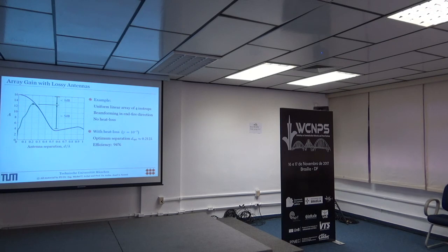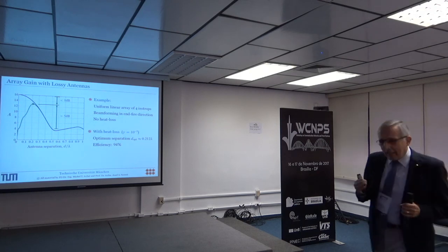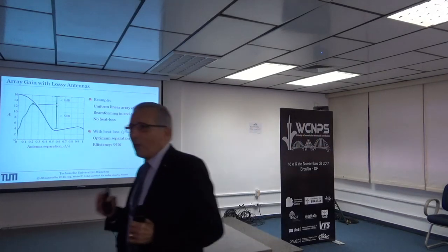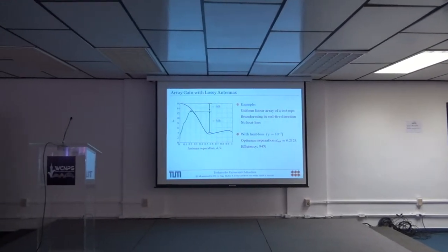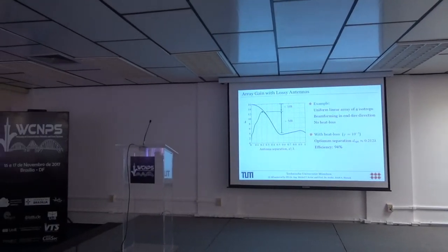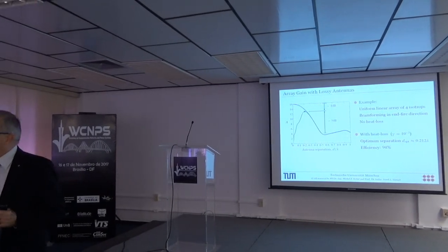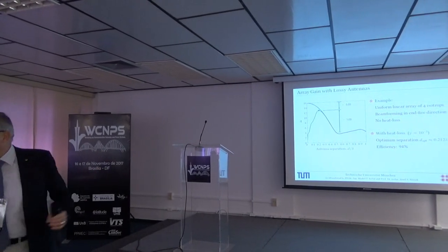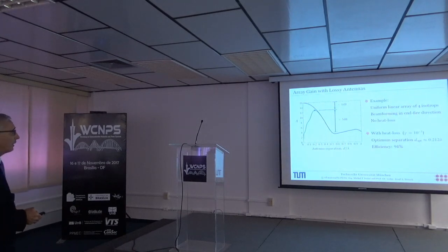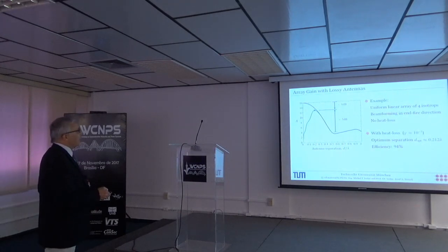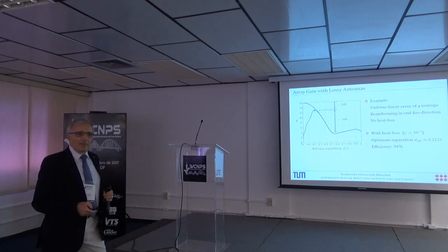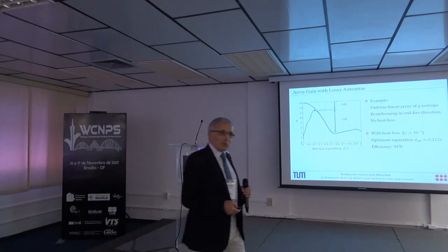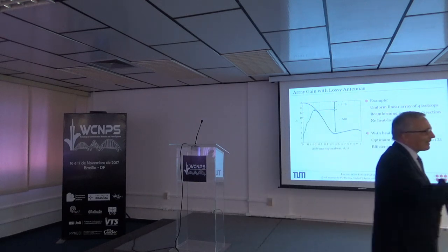One has to do 2 things to exploit that. We have on the one hand optimized the distance. What is the optimum distance I should choose? And in these distances I have to take into account that the design of the beamforming vector has to be optimized for that specific situation, including the losses. So it's not the same formula anymore, which I've shown just before. And what we see there, if I'm going for approximately lambda over 4 instead of lambda over 2, I can get almost all the gain which is there. And that is something which we should use in mobile communications, which would extend range.